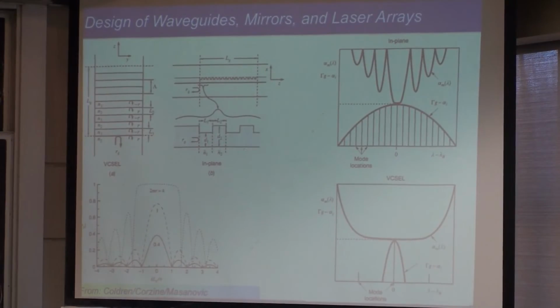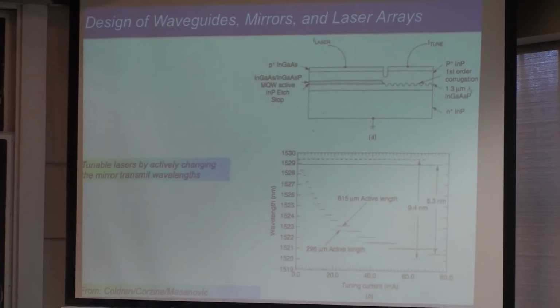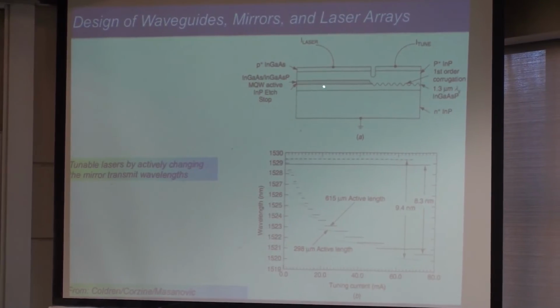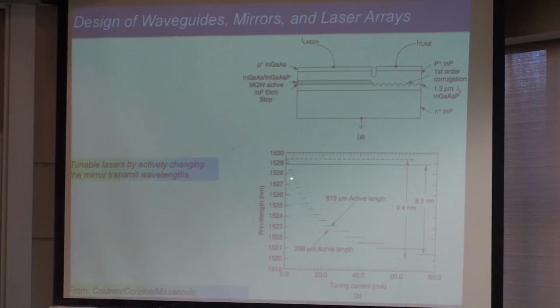Now if you can do that, you can do a lot of very interesting things. For example, you can take a laser emitting at, let's say, 1550 nanometers. These are communication lasers, like the lasers that feed photons into optical fibers, close to 1.55 micron. You can put a DBR on the side, which you have etched down to create a grating, and the light goes out and gets reflected, right?